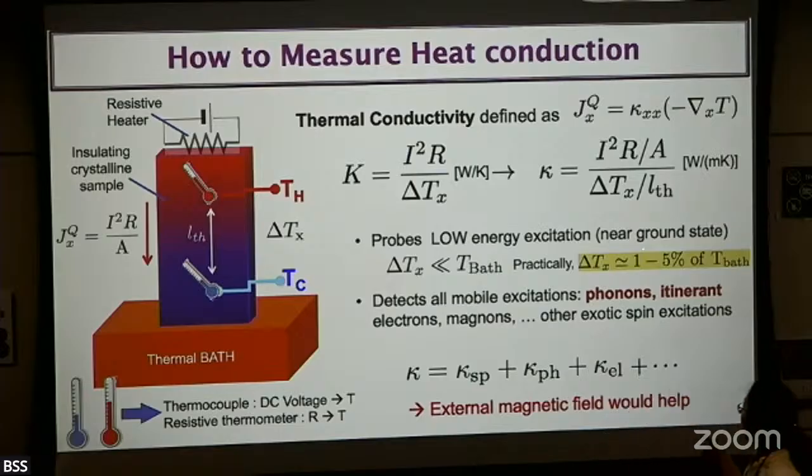That's right. So we are always checking this range. I'm going to show you the data and make sure that it's linear. As I said, once you see the nonlinear behavior, most of the time it is because your entire sink temperature is going up, the entire setup temperature is going up. I'm not saying it's impossible. I'm saying extra care has to be taken in order to distinguish heating versus nonlinear response.